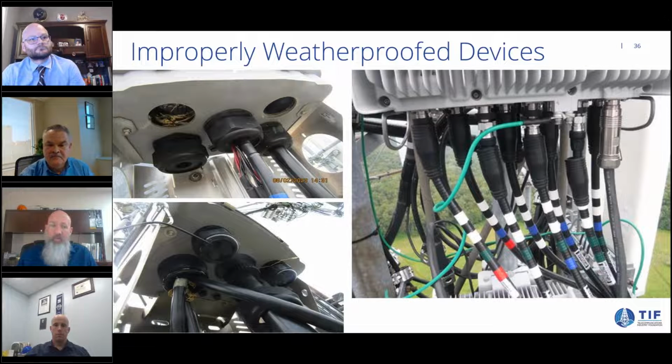Wide open overvoltage protection units and unweatherproofed RF jumpers could potentially lead to service degradation. And like John said, being that we are now taking 70% plus of all emergency service calls on cellular networks, this isn't just affecting our young men and women from being able to update a social media post. This is impacting people that could be in emergency situations.